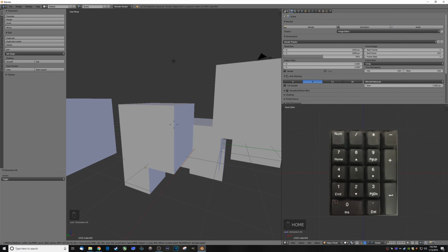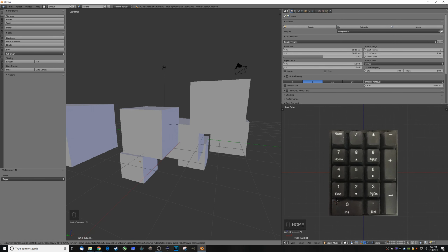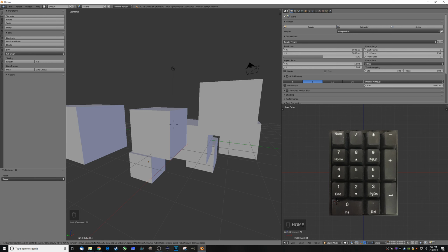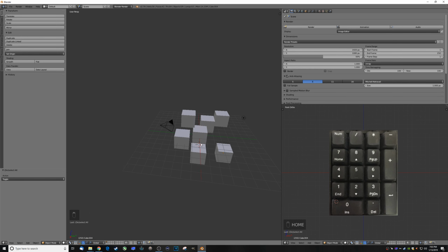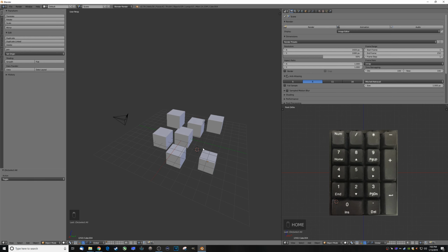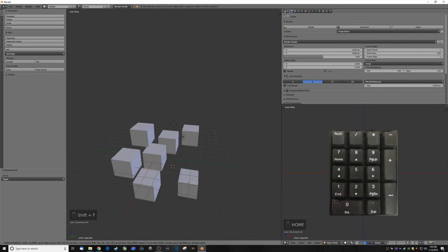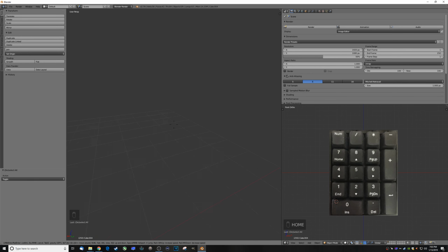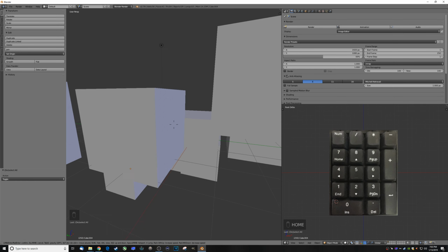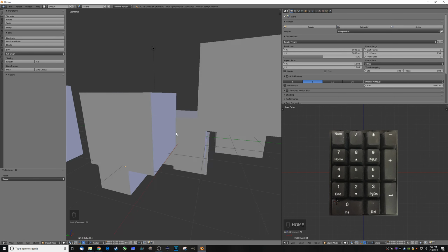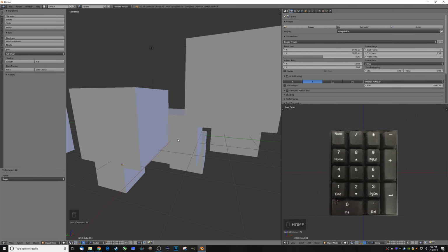Now, just like when you right-click and drag objects around your scene, if you right-click or press Escape, you'll leave this view and go back to where you were when you started. However, if you want to keep it and make it permanent, you'll simply position the camera and press Return or left-click, and then that is now where your 3D view will be.